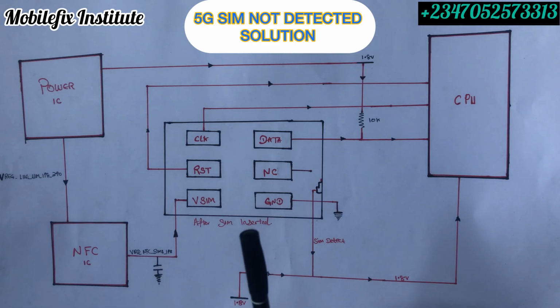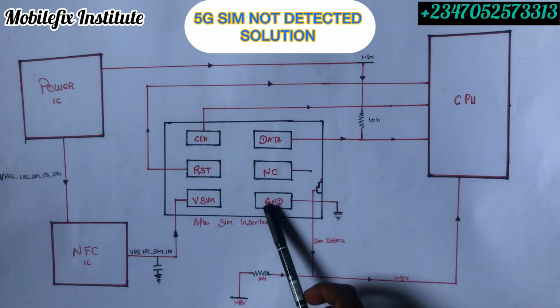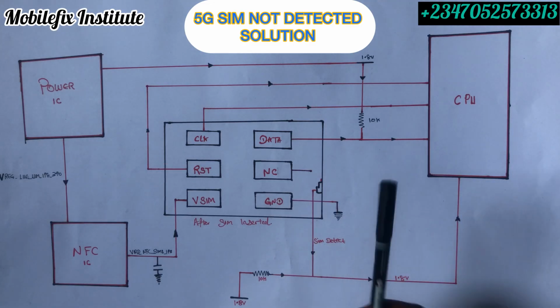Another thing that can happen is that any of these lines might be open. The ground might be open. If this ground is open, it will not detect your SIM. So you have to connect this pin to your ground.